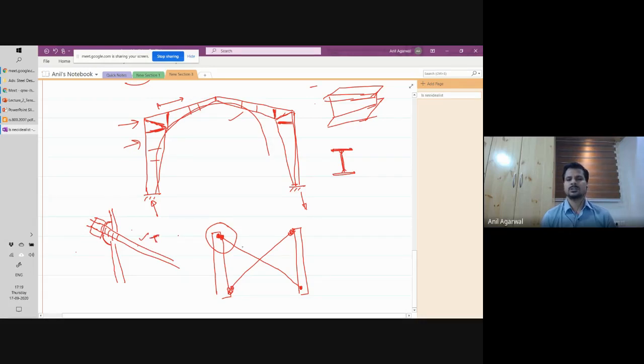Because the rod does not have any compressive strength, you pre-tension it so that it is in tension when the earthquake loading comes. So even if it goes into compression, what will happen is that this contact will be lost and there won't be any compressive force coming onto the rod, because it is only being pulled this way, right? So it can resist only tension. When the compression comes, it will simply separate and will not resist any compression. So that's how these systems work.